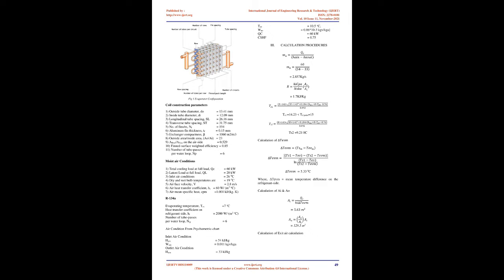Most refrigeration systems use a refrigerant expansion valve at the evaporator coil to sense the temperature of the gaseous refrigerant leaving the coil so as to regulate the amount of liquid refrigerant entering the coil. As liquid refrigerant passes through the refrigerant expansion control valve, part of the liquid flashes to a gas. Upon exiting, the refrigerant stream is mostly liquid but the vapor occupies more space. This causes the two phases to travel at different rates and separate, with the gas at the top and the liquid at the bottom of the stream. If this gas/liquid stream is not properly mixed and distributed, then some coil circuits receive mostly gas and other circuits mostly liquid. This degrades the heat transfer capabilities of the evaporator coil.